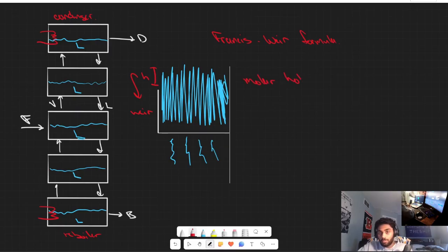And this property is crucial for determining our molar compositions as we go through our distillation column. The main factor that affects our molar holdup is the reflux ratio, which we have previously discussed is the ratio between the amount of liquid that we are sending down out of our condenser through the rest of the distillation column to continue the distillation process, as well as that ratio compared to the distillate leaving our condenser.